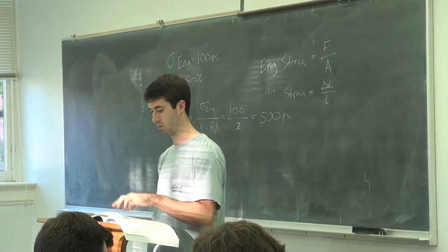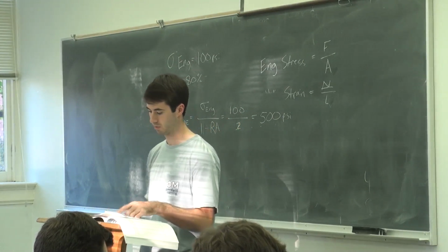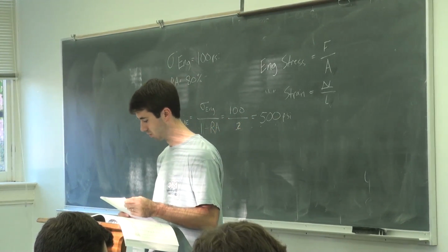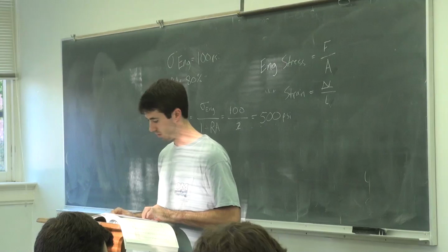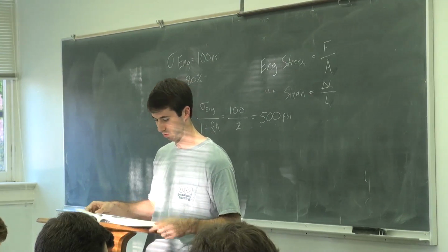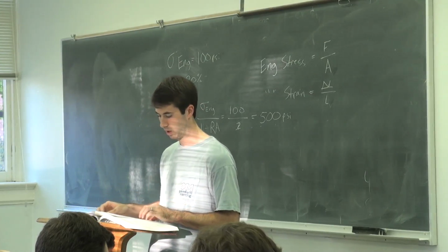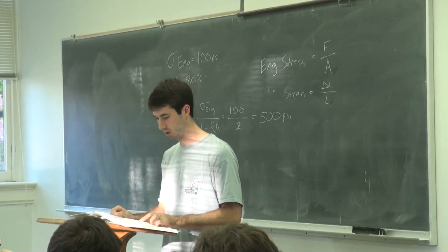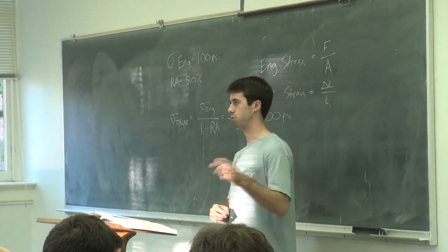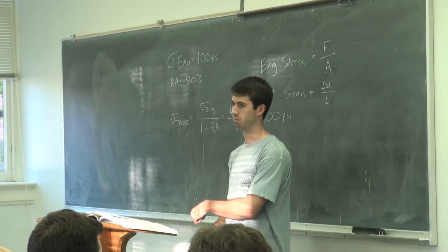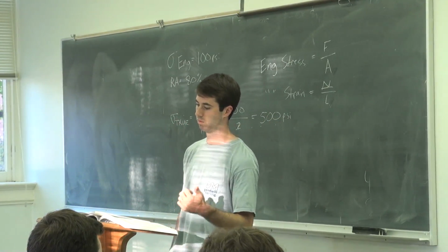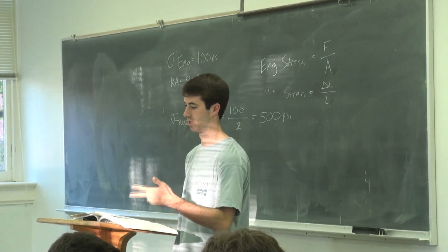So if we look at this pavement and we wanted to calculate a structural number, it's pretty simple. As far as these A terms, they don't give you a table of that. If they would give you that in the test, I don't know. But they're typically 0.11, 0.14, 0.44. 11, 14, 44, for your subbase, base, and an asphalt layer.